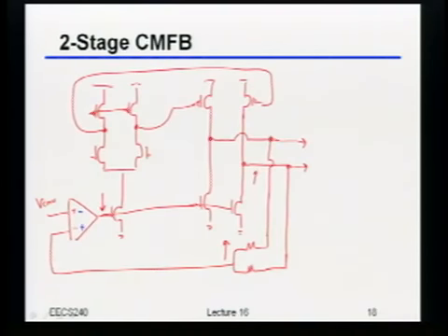So the first stage common mode will go up. Ah, okay. So you're already more sophisticated. So let's do the simple thing first. So if this goes down, what will these guys do? Drive the voltage up. Yeah, those will push the voltage up, right? Yeah. So I'll put that on both sides right there. Okay, but is anything else happening? And somebody other than Shiva, I guess?